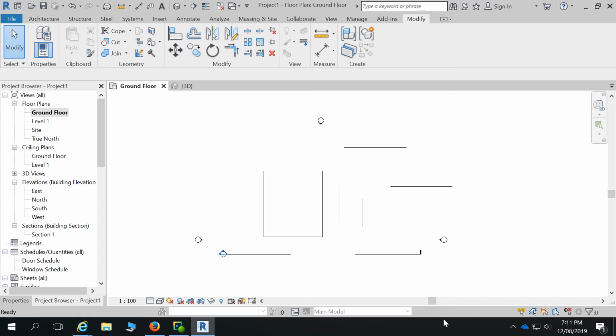So there are different modify tools that are there to stop other things happening. What sort of items do you think, if you're drawing a house, when you first start drawing a house, what might be the first thing that you'd ever pin? Walls? Yeah. External walls, as soon as you've set your building out, you'd probably pin those, because you've usually set it out in terms of the shape and volume of the building, and it might also be set out to the size restrictions of the block. So if you accidentally dragged it and you didn't know during the design process, you could get on site and not fit. Your site's so restrictive, you're building to the boundary and you've got a metre setback on the other side. It's not hard in a drawing to accidentally drag something. So once we've got those initial walls pinned, and dimensioned, they can't change.